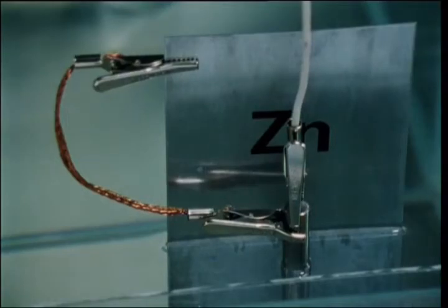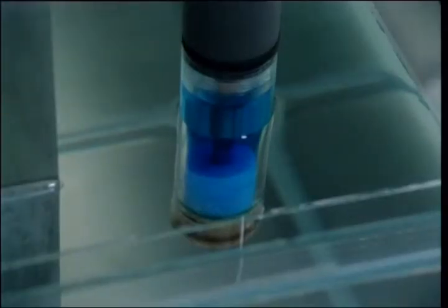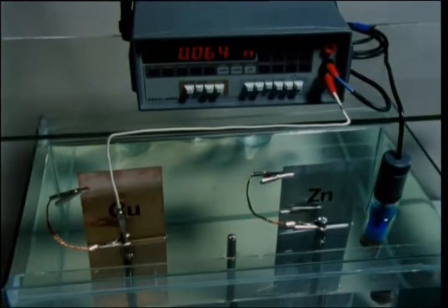In the couple, steel is the cathode and zinc is the anode. The steel is protected cathodically. There is a relationship between potential and corrosion rate, and in practice, the potentials are all compared to a reference electrode, in this case, copper-copper sulfate. When this is used with a voltmeter, the same changes are shown.